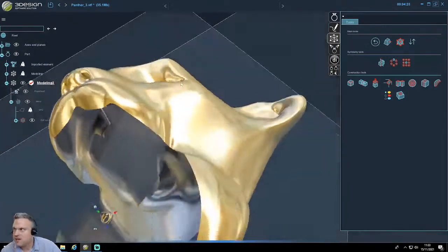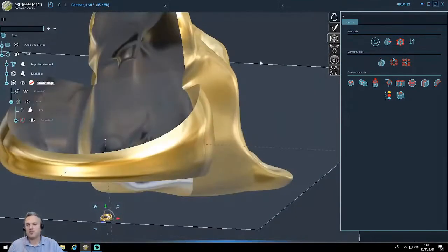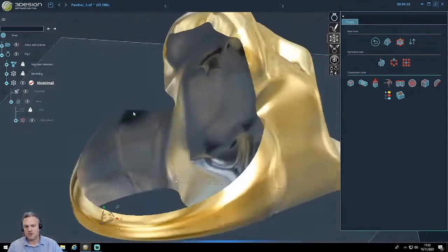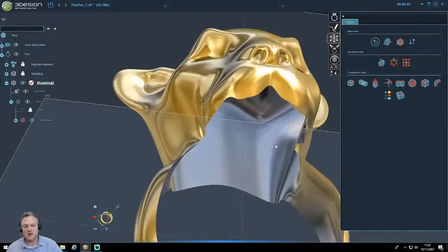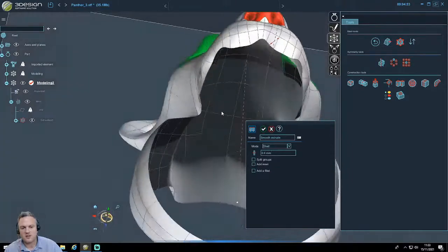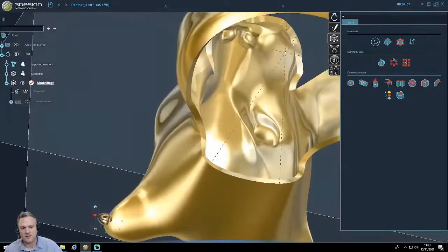So when this is modified, we want to have it in volume. For the moment, everything is in surface. You can see that my object is empty. I can create that offset through this feature, Smooth Extrude, and I decide which thickness I want. For example, I want to have 0.6, and automatically the software will create the volume through the thickness.